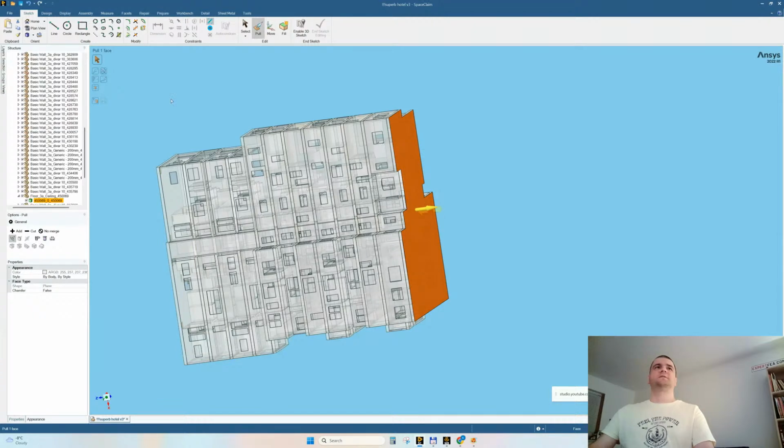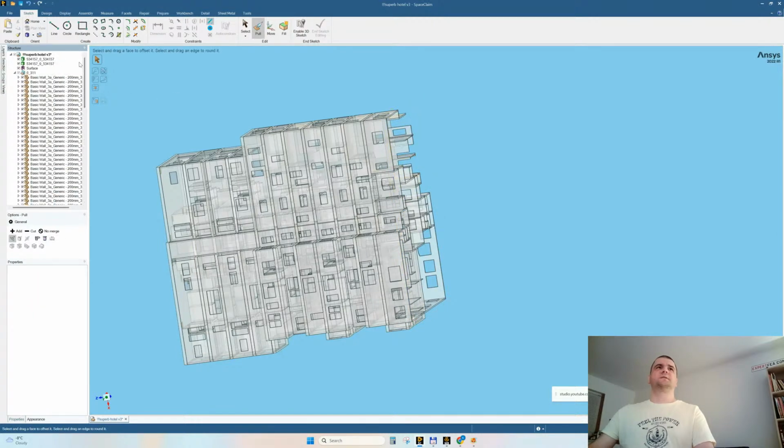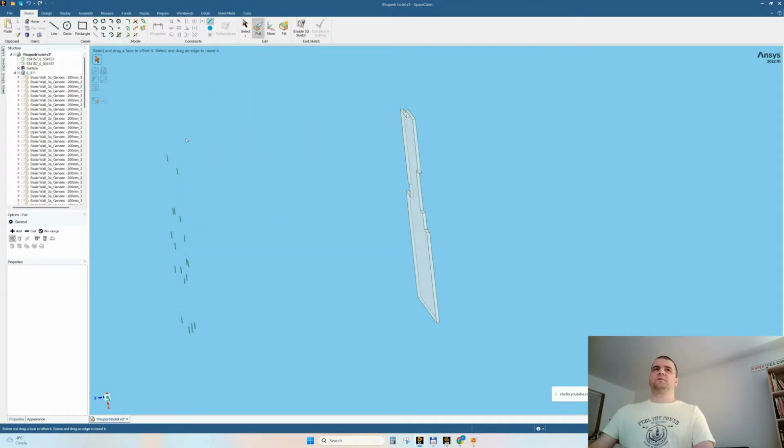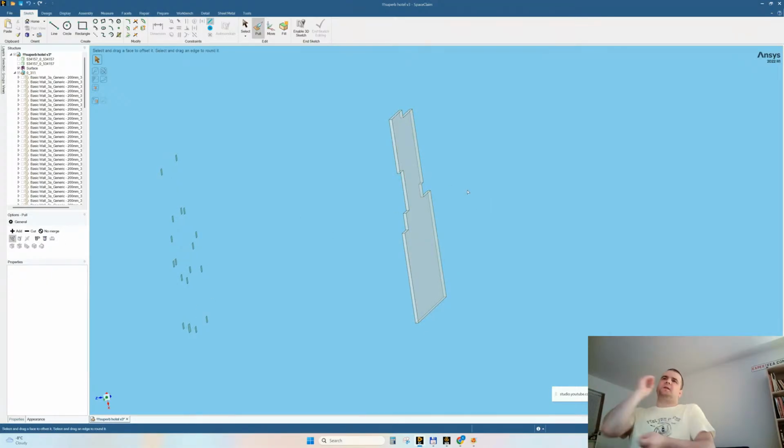Can I locate in structure tree? All right. I will hide this, the last floor. I will hide the surface. Right-click, invert visibility. Because I would like to extrude these until and more. I would like to bury them. Does it make sense? To bury them.